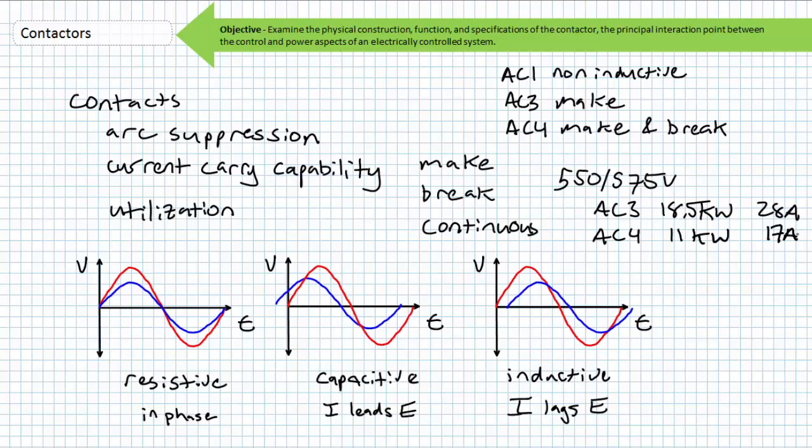This, depending upon your perspective, can be viewed as an advantage or disadvantage. A NEMA contactor, since it spans a larger usable range, will be more robust, however larger, heavier, and more expensive. An IEC contactor, since it is a special purpose built device, will be smaller, lighter, and less expensive. However, it is not as flexible nor robust over such a wide range since they are application sensitive. Finally, special purpose and solid state contactors exist, with notable differences between the ones I used as examples.